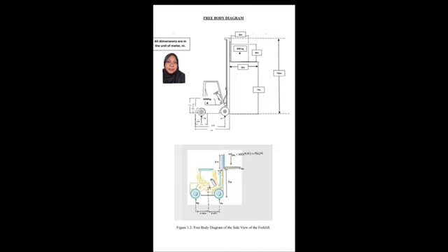Okay, as you guys can see, this is our free body diagram. All of the dimensions of the free body diagram are in the unit of meter, which is M. Then we can see that the weight of the forks calculated is 1962 Newton. Then it has a normal force on the front wheel and the normal force on the rear wheel, which is NA on the front wheel and NB on the rear wheel.